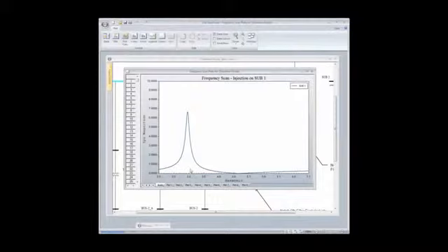In fact, my recommendation for anyone doing notch harmonic filter design is, if you have the ability to, move it away from an integer harmonic. Put the first parallel resonant point in between integer harmonics if you can. Now, when I say if you can, the reason why is the first parallel resonant point is completely dependent upon two things: the system short circuit strength at the bus where the filter is being applied, and the size of the bank. Those are the two key factors.